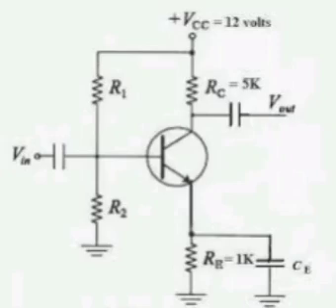Consider an ideal PMOS capacitor of area 100 micrometers by 100 micrometers operated at T equal to 300 K. Phi m, the work function for the metal, equal to 5.2 electron volts. X naught, the oxide thickness, equal to 3 nanometers, and Nd equal to 10 power 17 per centimeter cube.